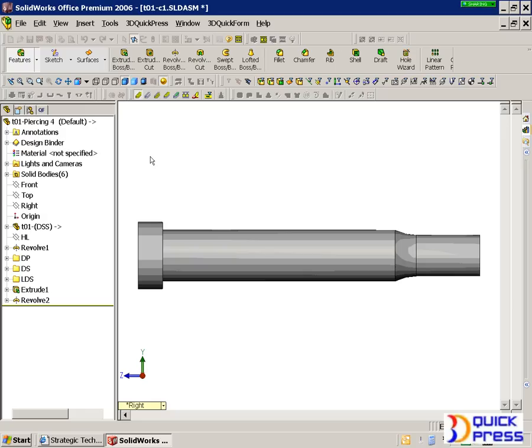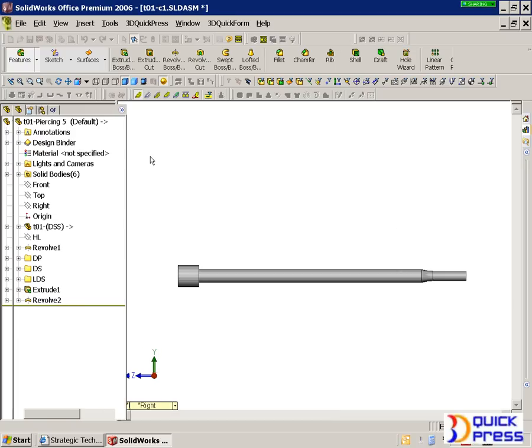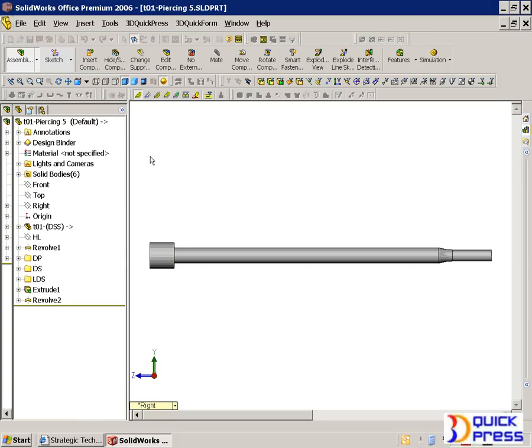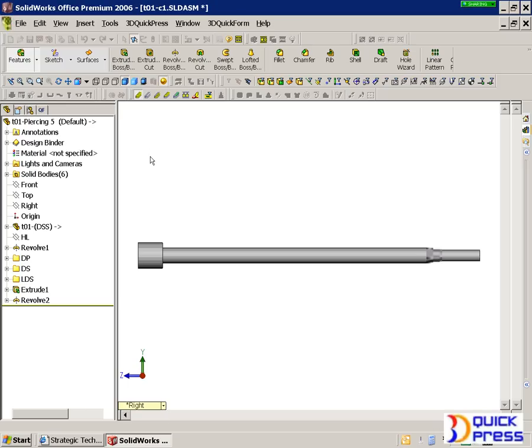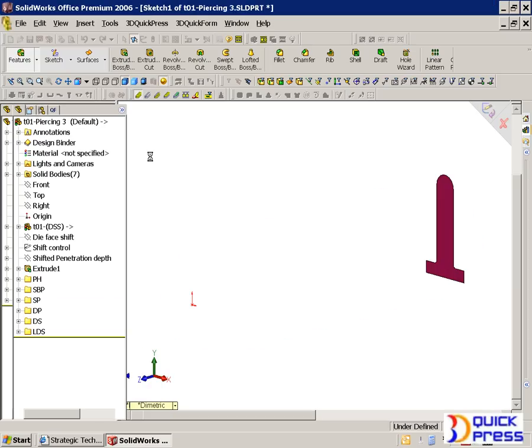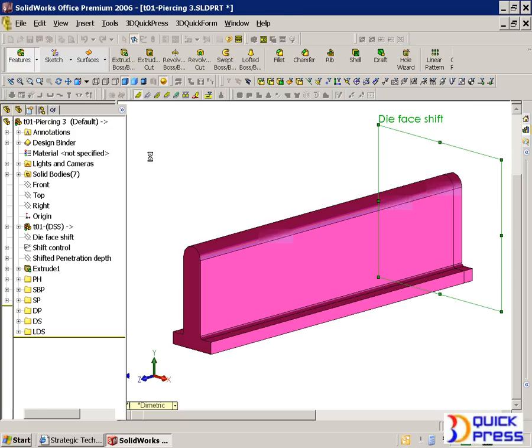The next thing it's going to do, of course, like I said, is build all the holes. Then it goes into the punch assembly and figures out what assembly it belongs to. Does it belong to the upper components, like the upper die set? It could be the lower die set or the middle die set. It rearranges itself. If it's a sub-assembly, it decomposes itself and then rearranges itself. Like in the case of a bending die, there might be a punch on top and a bend on the bottom. We need to dissolve the sub-assembly into 2 different areas. We take care of all this for you.